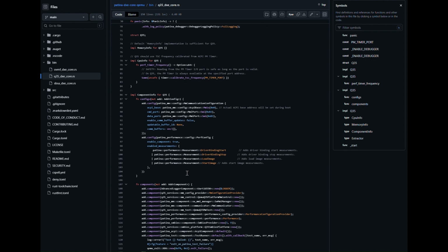So if you think about this, if you're familiar with Tiano Core firmware development, you might see this combining several different concepts. In Tiano Core firmware development, a lot of the configuration is specified in DSC files. So you'll have DEC defaults and DSCs that will give values for a specific platform, like which IO port to use and those types of details.